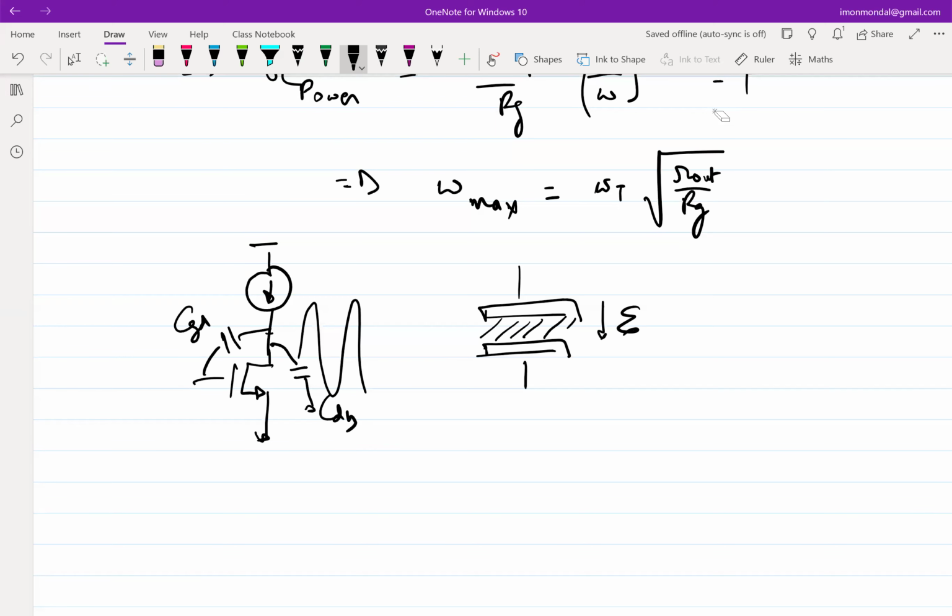If I take you back to the basic MOSFET courses, you want inversion in the channel, which means whatever electric field or voltage you apply at the gate should be able to create the inversion layer, and not only create it, for every unit change in the voltage there, it should be able to sufficiently influence the charge in the channel, right? So if you make a thicker and thicker oxide, without getting too much into details of the devices, the gate control of the channel reduces. That should make sense at a very zeroth order level, right?